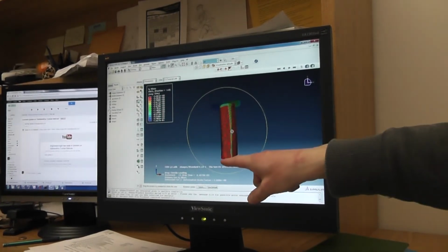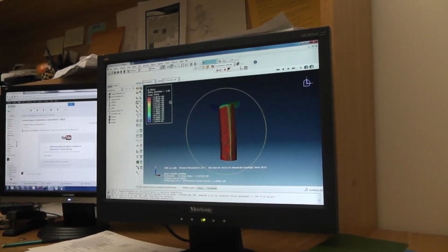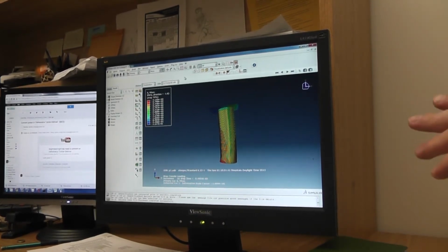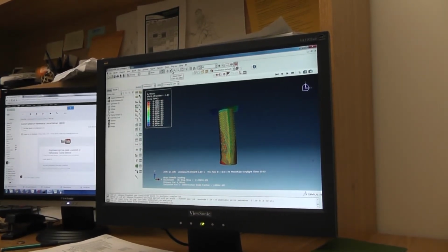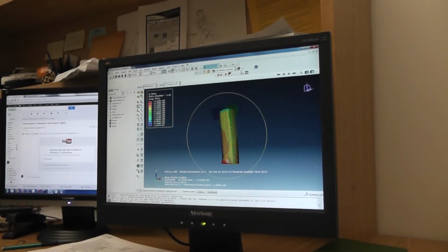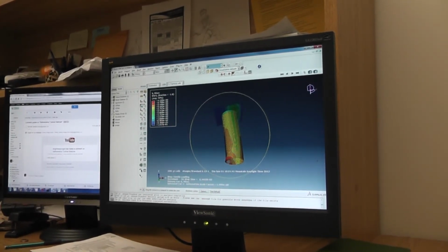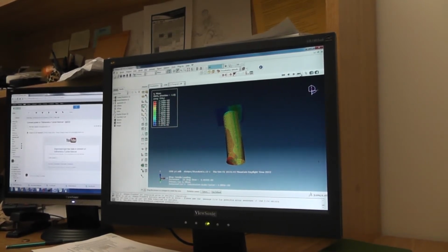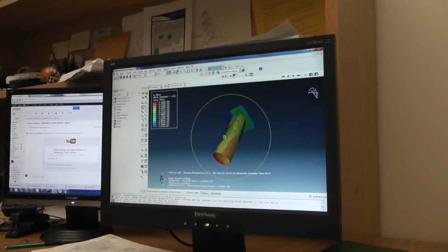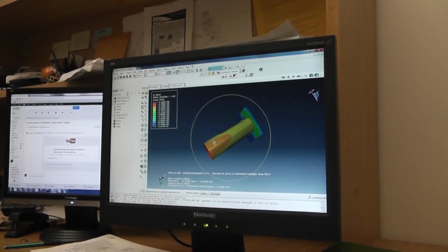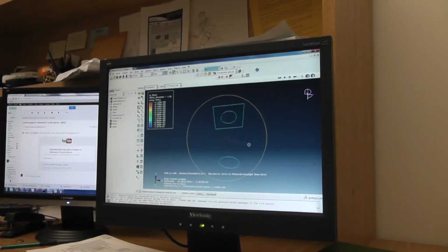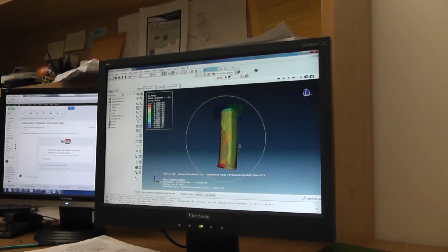Oh, it's failed here. It hasn't failed yet because failure is at 500, so... Look at the deformation. It's actually failing in compression, not in the tension side. But if we put a crack, it's going to be fine. Okay. We expect it to fail in tension sides.